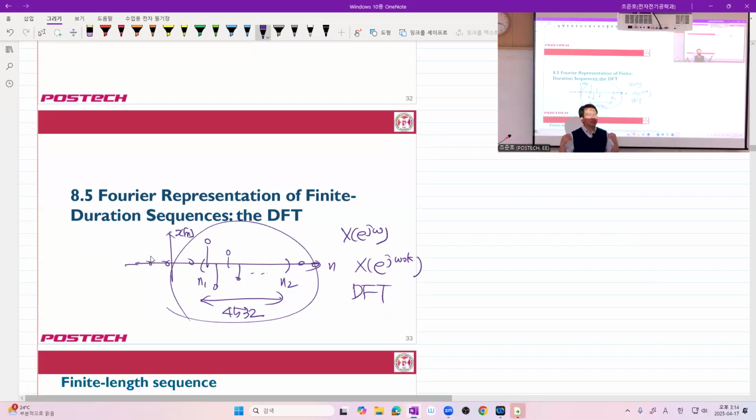Of course, we now have very large memory, but general DFT still requires a lot of computation. So we want to choose some n, that is, a 2 to the n DFT. So probably what you want to do is, okay, 1024 times what? 4. Okay, let me use a 4096 point DFT, which can be efficiently implemented using a fast algorithm.